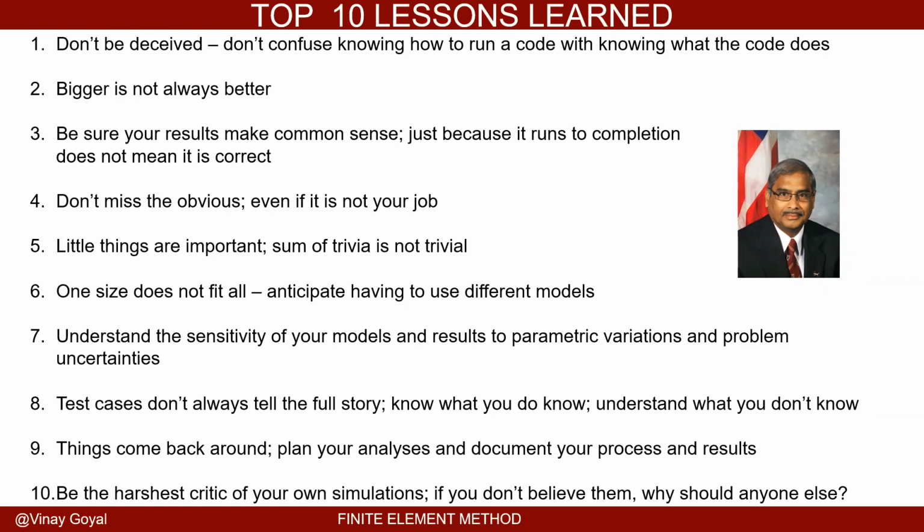A lot of these things look abstract to you, but as you go in your career, you will hit these things very often. One size does not fit all. Anticipate how to use different models. And a whole lot of times, as I said previously, if there is a fixed boundary condition, you don't need to put 6,000 elements there and set Young's modulus to a very large number. It's not worth it. You can just fix the degree of freedom and prescribe those displacements to 0.